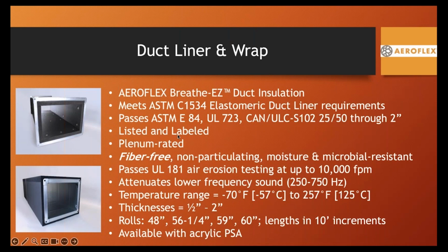And I want to take a minute to comment on plenum rated because we receive that question quite often. When you're asked if an installation is plenum rated, it can be answered two ways. One is, does it pass 25/50? Yes or no? If yes, then maybe the correct answer is plenum rated.